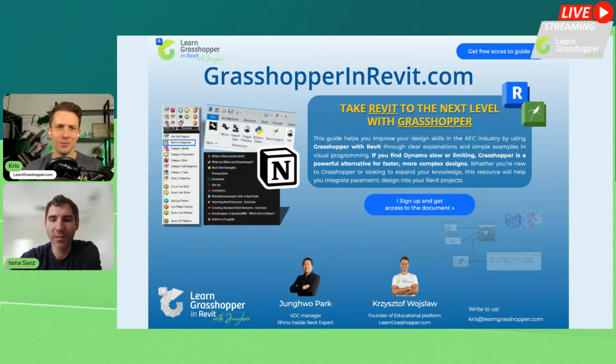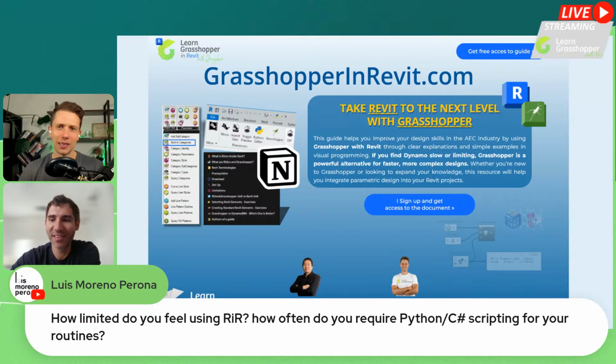We have a question from Luis here. How limited do you feel using Rhino inside Revit? How often do you require Python or C# scripting for your routines? Yeah, that's a good question. I think Rhino.Inside.Revit has, as I was saying before, a lot of components. You cannot do everything, but you can do almost everything using the native components. The cool thing is that you can use Python or C# to access the API and then control Revit more programmatically.